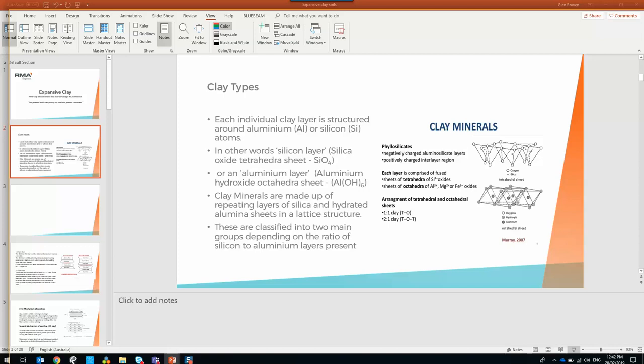Now typically when I'm designing piers in black soil, I just ignore the end bearing, because you can't reliably check that they've cleaned the holes out. If you ever look down a 5 metre hole in black soil, there's not much to see. So typically you get about 100 kilonewtons working load out of a 300 pier and 200 out of a 450 pier. And you might use 200 kPa end bearing, which technically you could probably push up to 600, but use about a third of what you're allowed, and that'll get you a safe design.